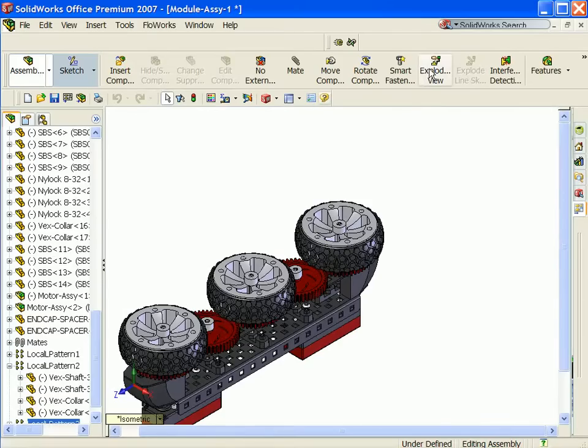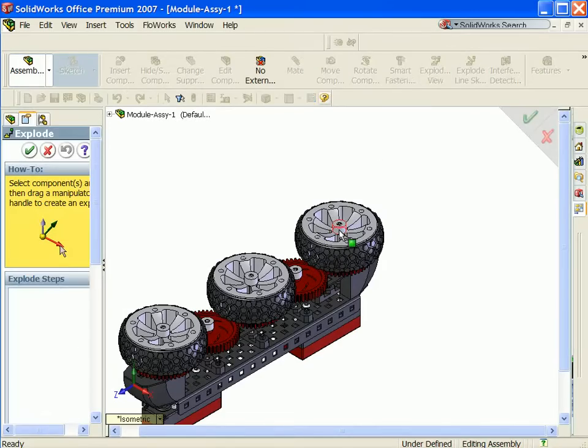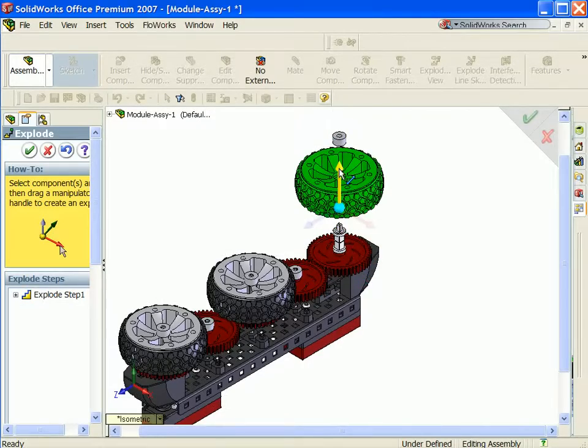You can utilize Exploded View to make sure all your components can be assembled, but you want to disassemble in the order in which the components would be added. So for instance, I am first removing the collar, then I will remove the wheel and tire.